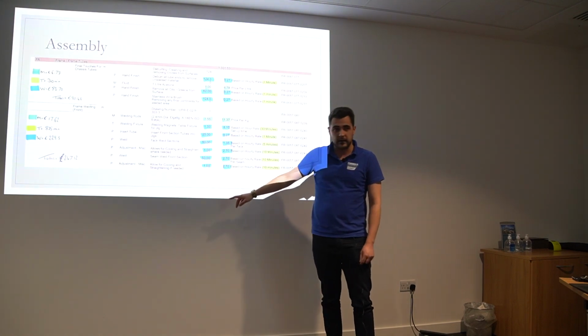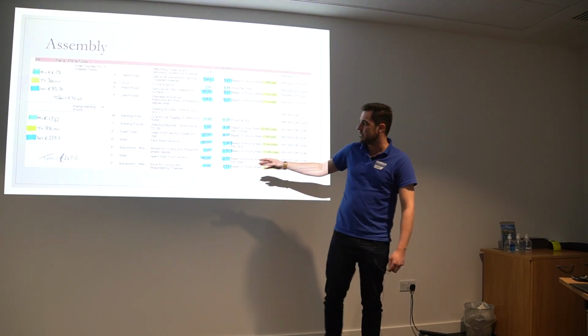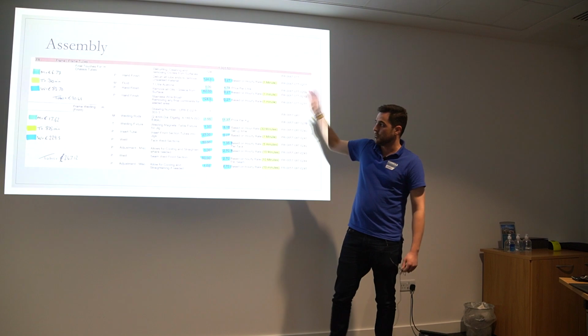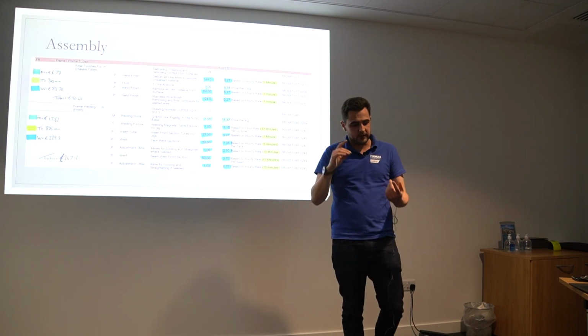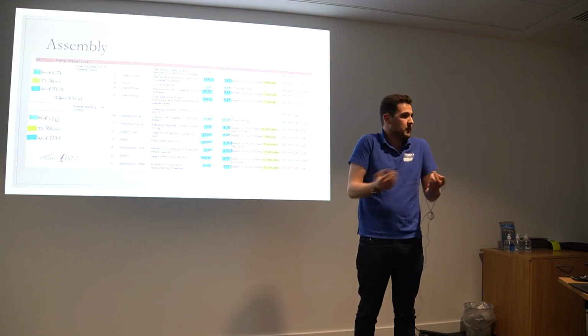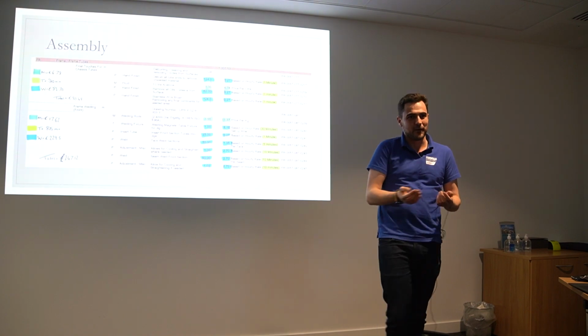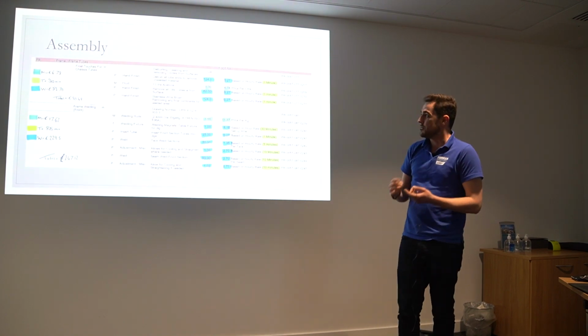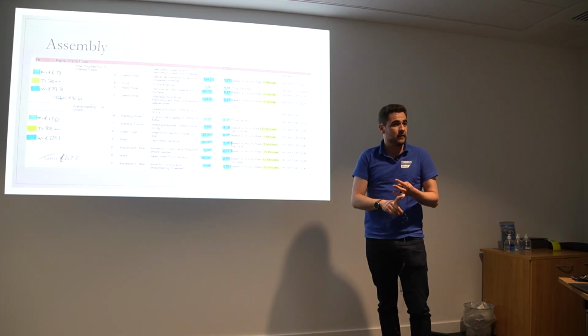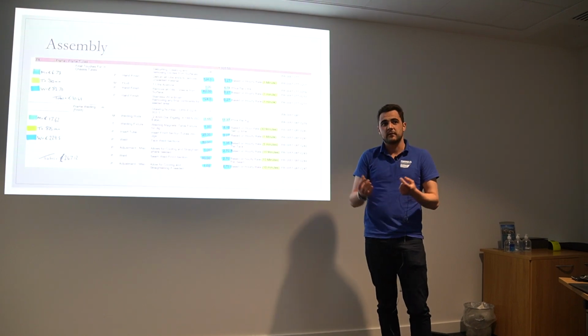Lower than that, you're also going to have inspection, which is something that was added on the very top level of all of it. So you might do dye penetrant testing. Make sure that, you know, welds are actually going to hold together when you go around the track. You might do destructive testing. You might just scan it in and compare it to the CAD model, but make sure there are some sort